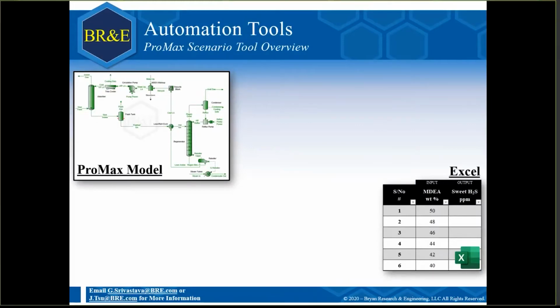Now, your supervisor asks you, when should I top up the MDEA? Well, in this particular model, we have a constant makeup stream that feeds in small amounts of MDEA to make up anything lost. But in reality, you don't have a small pipe feeding small amounts of amine constantly. You just periodically dump a bunch of it. And so as you lose amine, your MDEA strength actually drops. And what lower strength means is higher loading, worse H2S capture, and you are tasked to determine at which point does it start to become unacceptable.